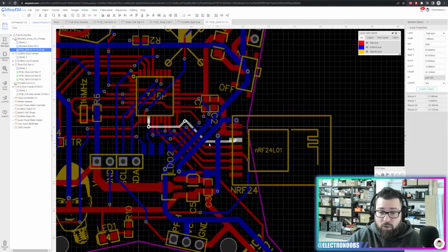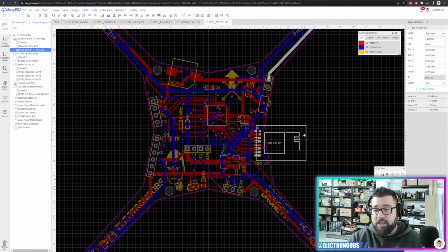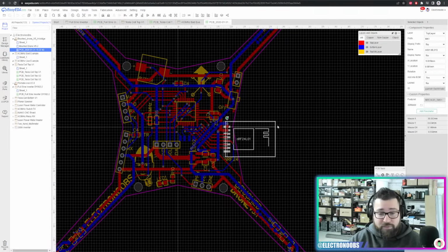At the same time, you also have to be sure that you add a lot of capacitors at the input, so the supply of this device is very stable.